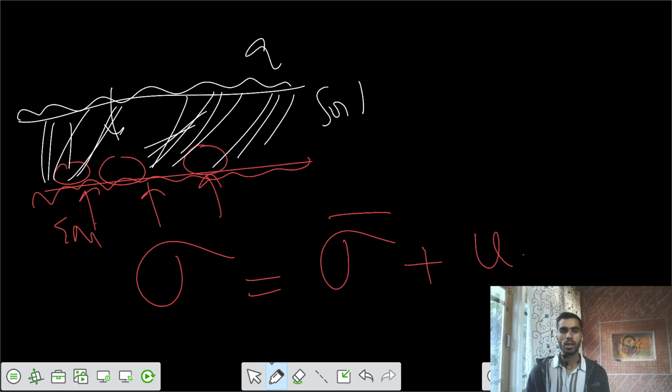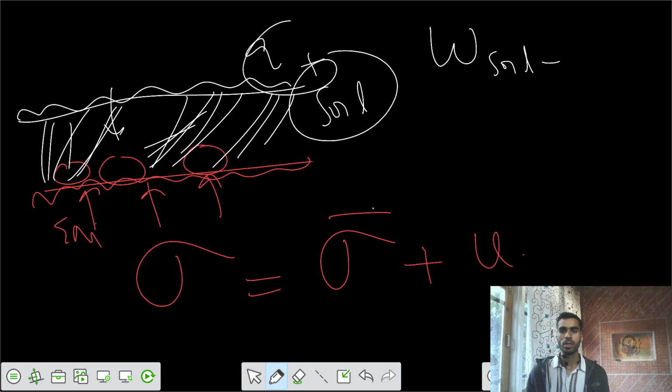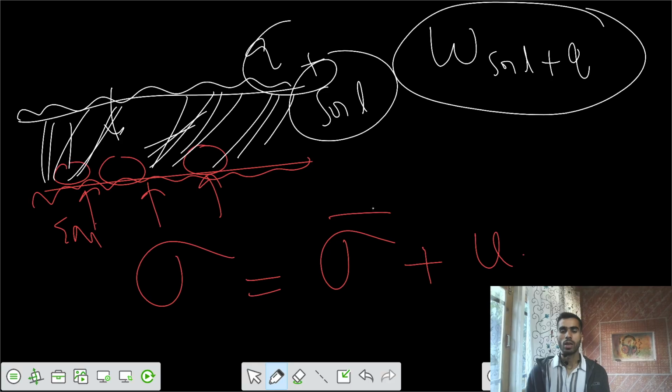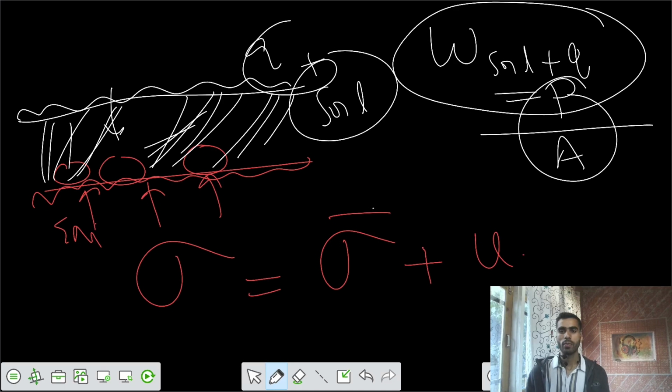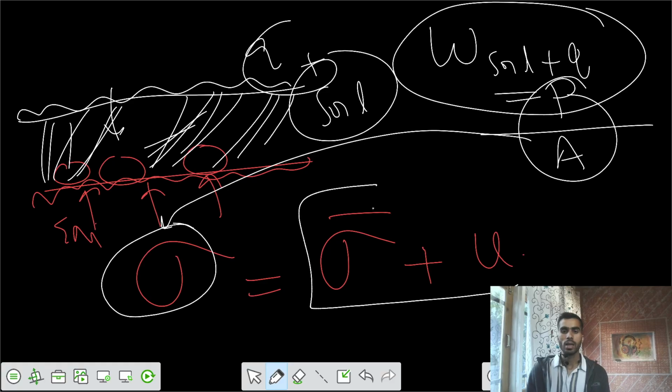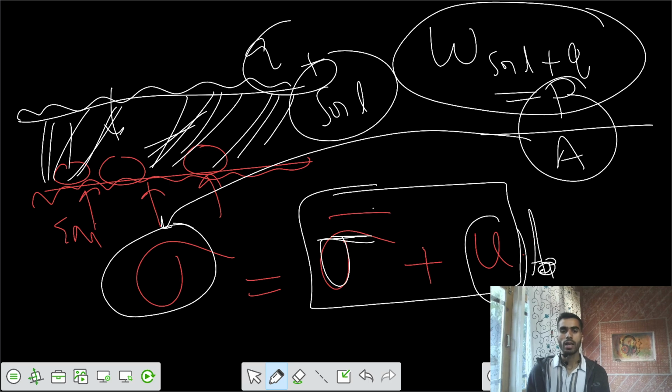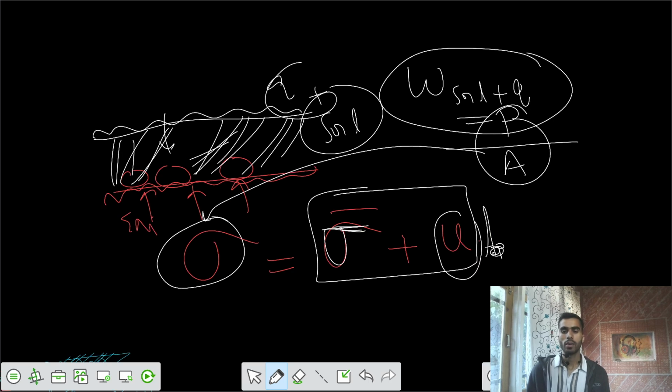There was some soil, there was some surcharge also. So the weight of the soil plus surcharge equals some value of total P, and divided by the area of cross section, that will give me your value of sigma, and that is resisted by pore water pressure into the area of the pores, and your effective stress into the area of the total cross section.